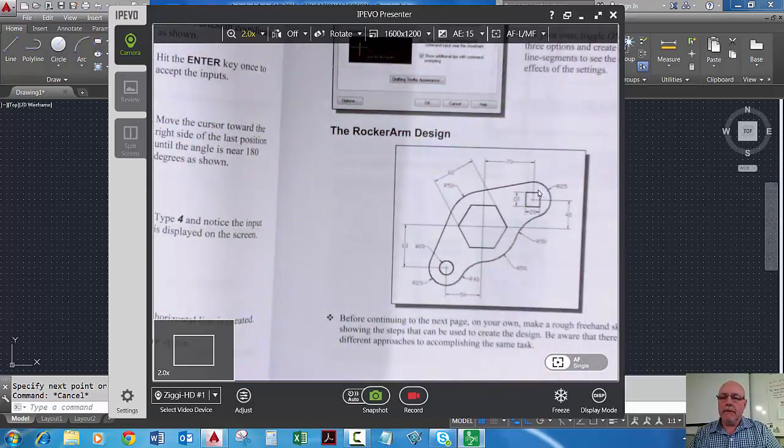So we've got a square to place and a circle down here. Then we're going to use the specialized circle to create a tangent radius. Okay, so tangent in two places and then provide a radius for the circle. We'll also use the tangent snap to attach a line that's tangent to this arc and that arc. And we'll use a lot of trimming.